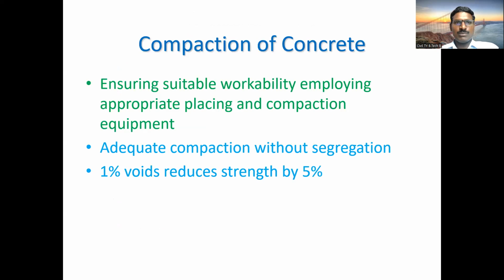Then compaction of the concrete. As we have learned in unit number 2, and in this unit also, compaction of the concrete. There are various methods of compaction of concrete, and we have to use a suitable method. We have to use the needle vibrator, table vibrator, and surface vibrator. All these vibrators we use for the compaction of concrete.